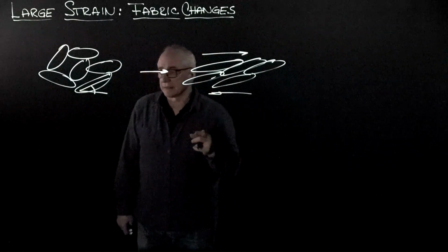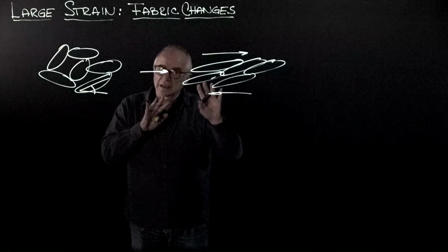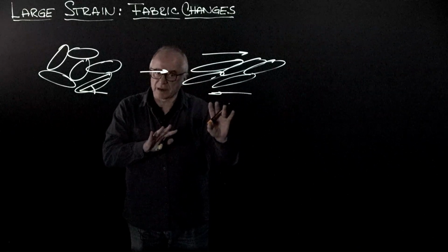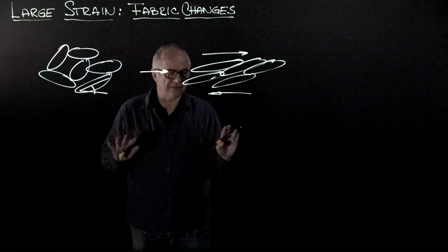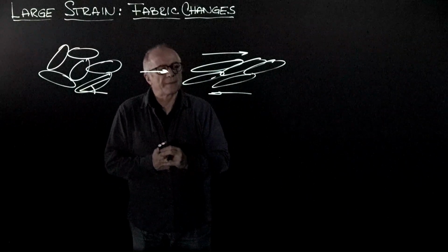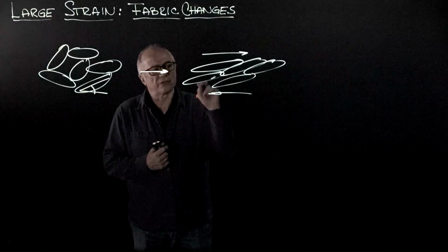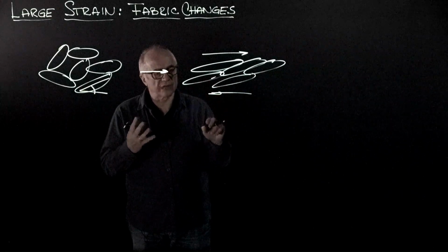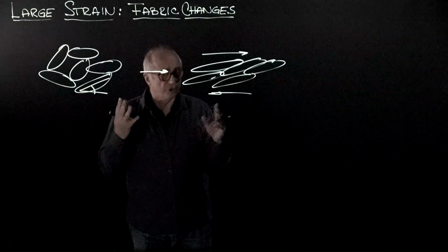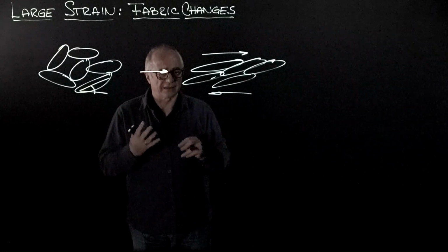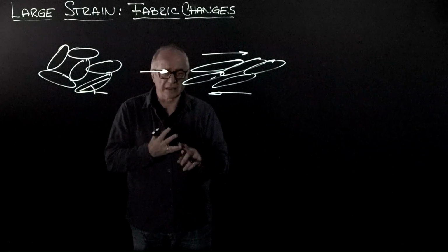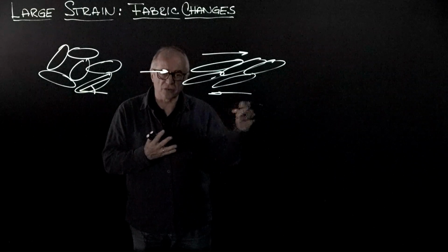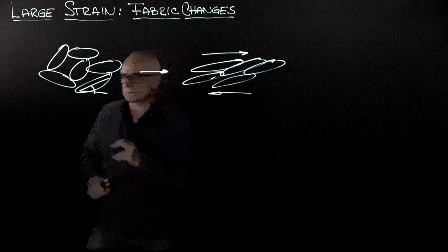The other example, so now if we study elliptical particles, and a very minute amount of ellipticity has a dramatic effect on the soil. So if we are going to summarize this, we're going to have 4 polar diagrams: the histogram of contact normals and the particle orientations, and then the polar diagrams of mean normal and shear forces.